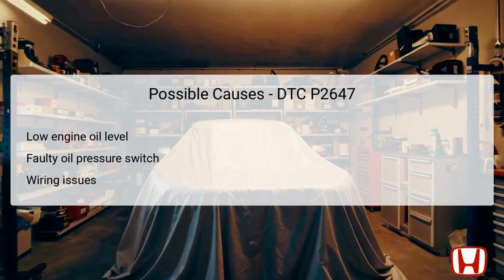Thirdly, wiring issues such as damaged, corroded, or loose connections between the rocker arm oil pressure switch and the PCM can lead to high voltage readings. Each of these issues must be carefully examined during the troubleshooting process to ensure a proper diagnosis and effective resolution. It's critical to pinpoint the cause before any parts are replaced, which can save time and resources during repair procedures.